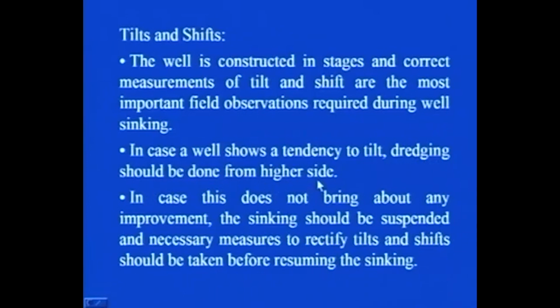Higher side means the side which is going less below the ground surface. So if you see the cross section in the vertical direction, you will see the 2 well steining. So while you go for dredging, it can happen that if tilting and shifting is taking place, one side can move more in the vertical direction and one can move lesser.